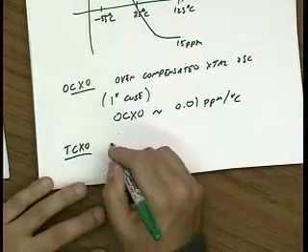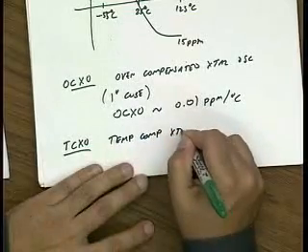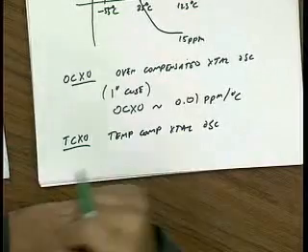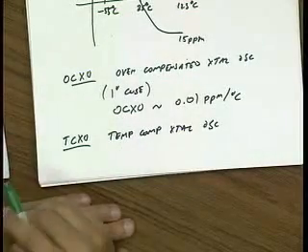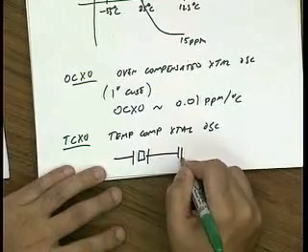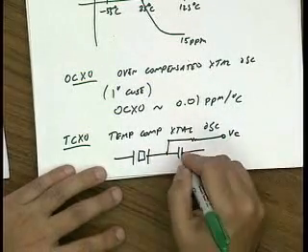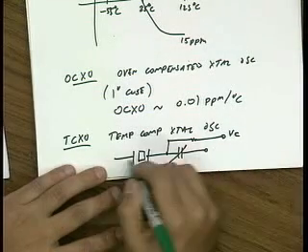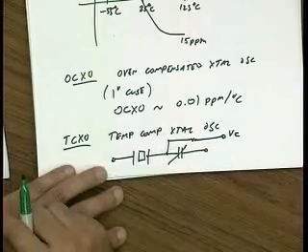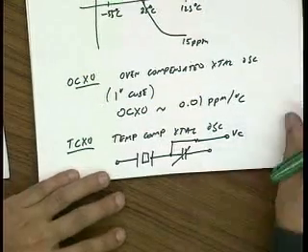More common is actually temperature compensated crystal oscillator. And this goes back to what Michael Mark pointed out, is we can use an external capacitor to basically tune the resonance frequency. So here I have a control voltage, say this is a varactor, and I'm going to pull the frequency of this circuit. So how do you come up with this voltage?